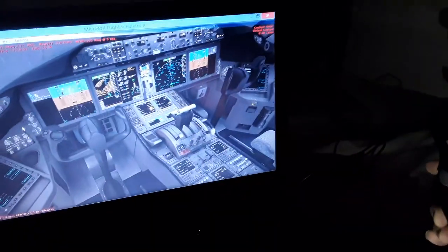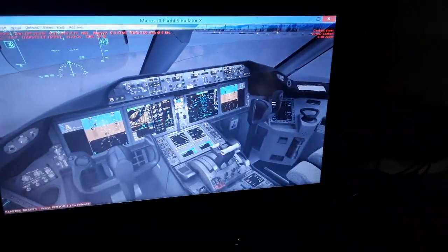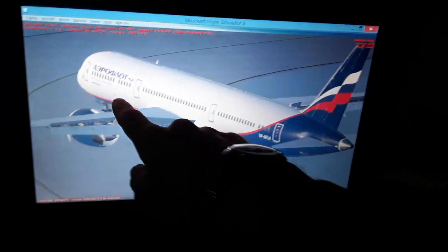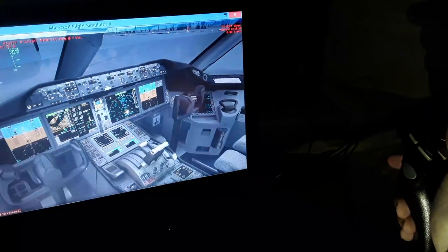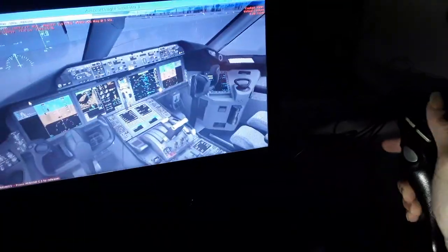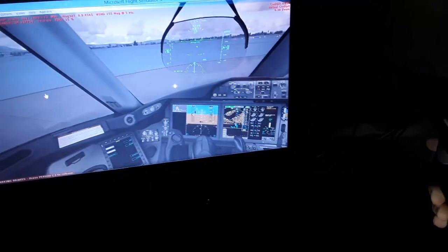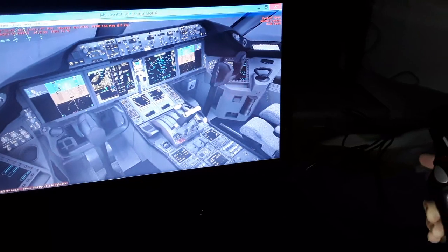You can also see the rudder pedals, which I forgot to mention. We have the rudder, and also the tiller here, which controls the forward nose wheel. As we fly, you can see the forward nose wheel and the rudder together in the rudder pedals. The nose wheel deflects 76 degrees left and right. On the ground, it decreases as you increase speed for takeoff, to 7 degrees deflection at around 45 knots.